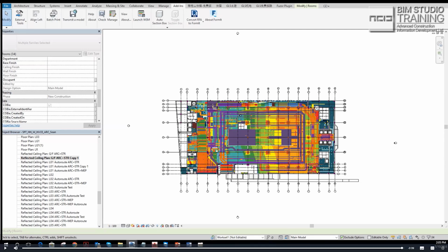So if I run from here to here, and I know my own size, I'm trying to find a space I can mingle the shortest distance without hitting the below ceiling and above beam. So if I run my first pipe, and then a second pipe, with my obstacle, I try to avoid it. Instead of clash detection, I use clash avoidance. Avoid the clash. Then there's no need to do the clash detection.